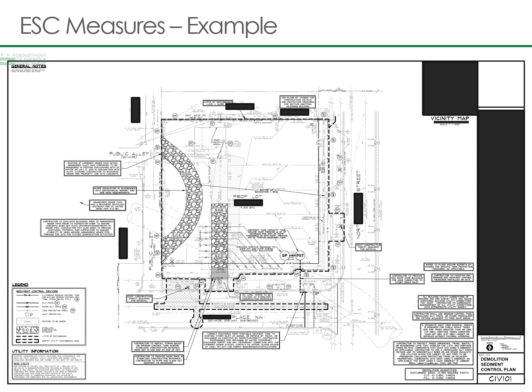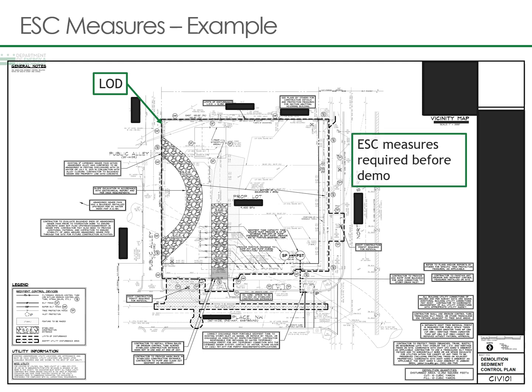First, let's look at the demolition plan. So many designs are going to require some demolition on site. You have to show the limits of disturbance on all plan sheets, so that includes the demolition plans and all erosion sediment control, so the plan reviewer can see across sheets all of the work proposed, including the demolition work, included within the LOD.